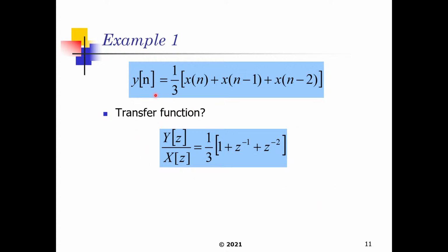So it's just a direct transfer function realization when you watch it here, because this difference equation form is basically equivalent to the open form solution that we saw in a few lectures back. So we can just eyeball this and just do the z transform of this equation accordingly.